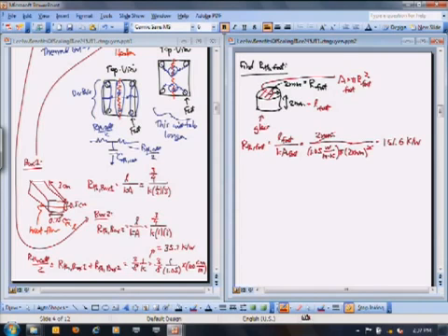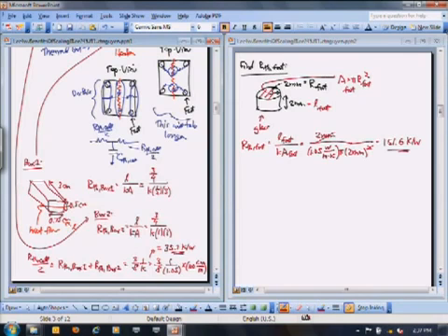Okay, so this foot has a lot more thermal resistance, if you look at this, than the cell. That makes a little bit of sense because the cell has a lot of width. It's pretty short. It's just not that long, it is longer than the foot, but it's still very wide. So there's a lot of conduit for heat to head toward the feet there. Now, my calculation is a bit wrong because I didn't separate it out into these 4 quadrants here. I didn't do this problem. I just did that problem there. Okay, so it's a little bit off, but it's going to give us a pretty good ballpark answer there. And so I have the resistance of the foot.